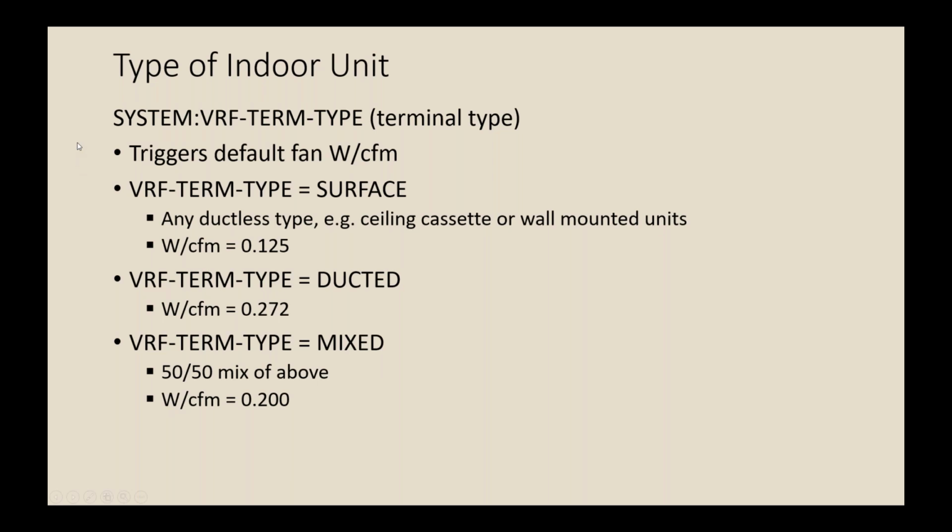The next item you need to pay attention to is the fan power of the indoor unit. This is handled in a kind of simplistic way, but probably a reasonable way in DOE2, by defining for each indoor unit a terminal type, or VRF term type. That terminal type will trigger some default value for the watts per CFM.